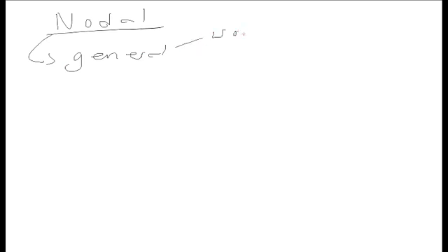all the same. I'm often asked, which method should I be using? The answer, almost always, is nodal analysis. Nodal is general. In this course, it will work for any circuit. Sometimes, nodal analysis isn't enough. You may need to use, for example, the relationship between voltages and currents in dependent sources in order to get an extra equation. But nodal is always a starting point.